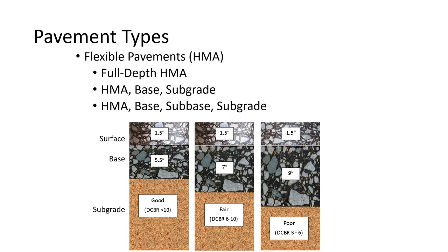And our technical term for asphalt is HMA, hot mix asphalt. So this means that they heat the aggregate and the liquid asphalt oil basically up to a certain temperature and mix it together. That makes it hot mix asphalt, HMA. So on your plans, at least in Indiana, you're going to see everything listed as HMA, right? The other option is PCCP, which is Portland cement concrete pavement. So that's the other material, right? So it's either black or white. That's our two choices generally.